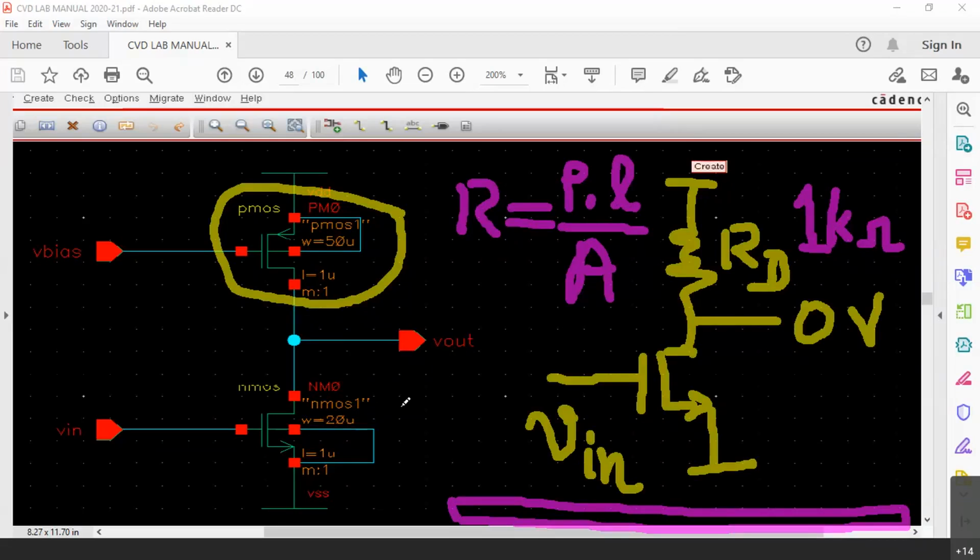So in general, inside the chip, if capacitors are required, it may be in general femtofarad or attofarad, at the most picofarad, not even nanofarad. Forget about microfarad. So if a chip requires a microfarad capacitance, they will simply bring the pin outside the chip, and you will have to physically connect to an electrolytic capacitor outside the chip. That is what is the approach.